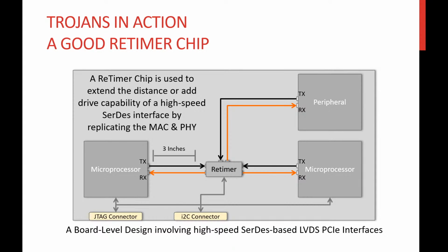So, for example, a 2.5 gigabit signal can travel further than a 25 gigabit signal. Note also that the board subassembly here is shown with a JTAG port and an I2C port. These are both test and settings configuration ports that are used to put the chips into various test configurations, or can also be used to select operation modes.